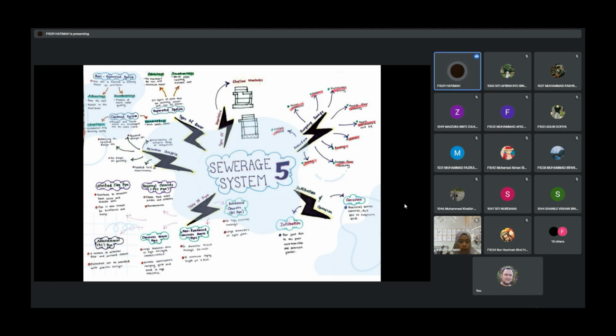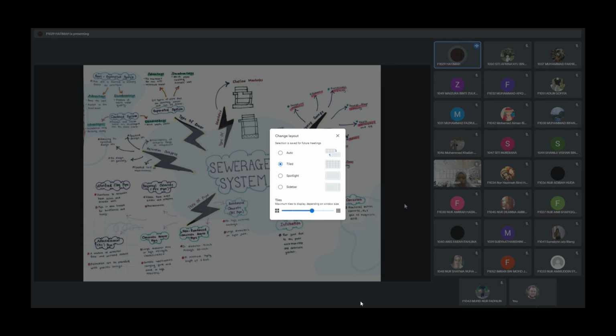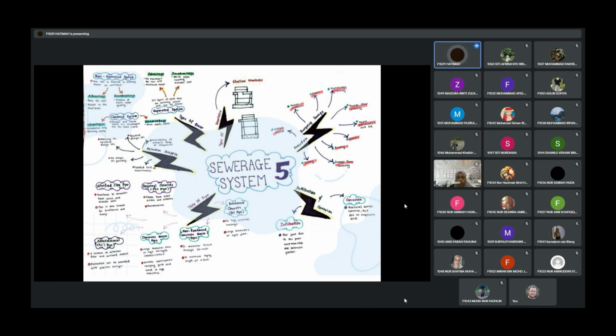Next subtopic is type of pipe. We have vitrified clay pipe, polyvinyl chloride PVC pipe, asbestos cement pipe, concrete sewer pipe, non-reinforced concrete sewer pipe, reinforced concrete pipe. And then we move to infiltrations and corrosions, and then the procedure of designing sewage based on the design period, sewer diameter, sewer bending, preliminary study, sewage flow velocity, depth, excavation and fill, zoning, joint, and lastly sewage flow quantity.